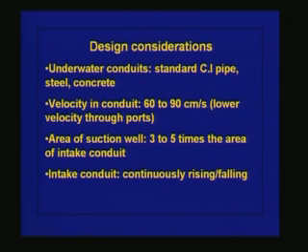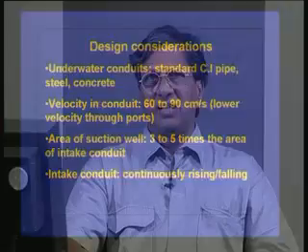The intake conduit itself should be continuously rising or falling. It should not have any bends, because any bends will cause flow disturbance and it will increase the head loss. That way the water level in the intake for a wet intake will be much lower than the water level in the river, and that is not what we want. So the intake conduit should be either continuously rising or continuously falling.